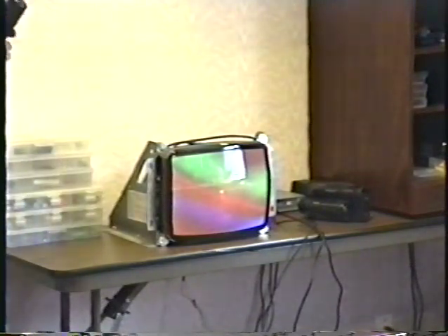And sometimes you'll see this, especially in cocktail table games. You'll have a cocktail table game, it'll be set in this direction, it'll look perfect. You turn it 90 degrees, and the colors are all messed up. And the reason for that is that it's just the magnetic field of the Earth that's messing it up. Well, we have games in 7-Eleven stores. They're on 24 hours a day, 7 days a week. The degaussing coil never operates in the 7-Eleven stores, because the games are always turned on.